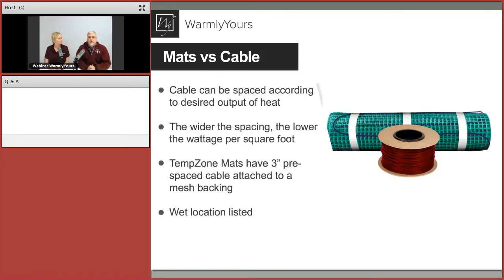And that's why they're mounted on the mesh in the way they are, because we know they'll always be 3 inches apart. There'll be a nice even heat, and you want to make sure, even if you have 3/4 inch wood, if you get that up close to where your feet are, you can see that you're going to be within an inch to an inch and a half of that wire.